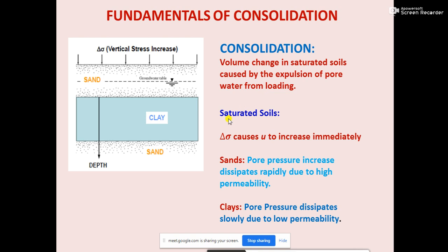In a saturated soil, the pore spaces will be filled up with water, right? So whenever an external incremental load comes onto the soil, at that time the water at first will try to take up the load, all the load, right? And later what will happen,